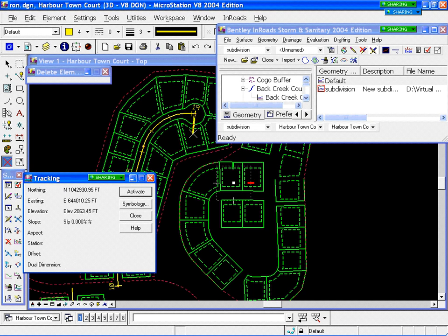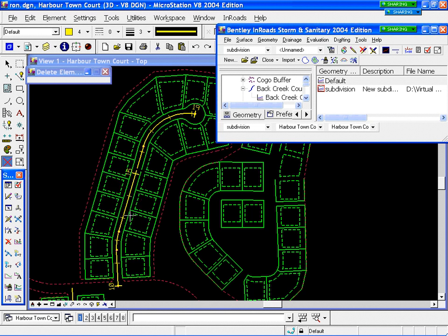And you notice that even though my tracking is at my top station, my ground line is 63, and I'm going downhill as my screen looks. So I'm just downhill to the screen, to the south there. And so I actually need to lay out my network from high station to low station, to flow it down at the bottom of my system here.